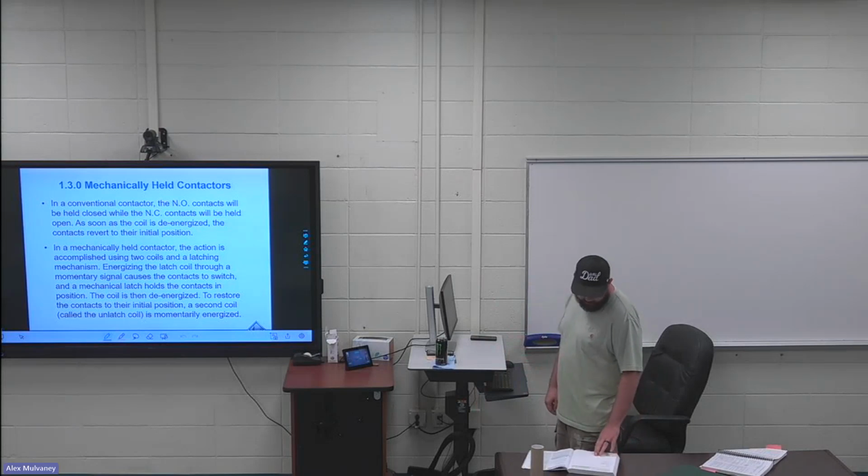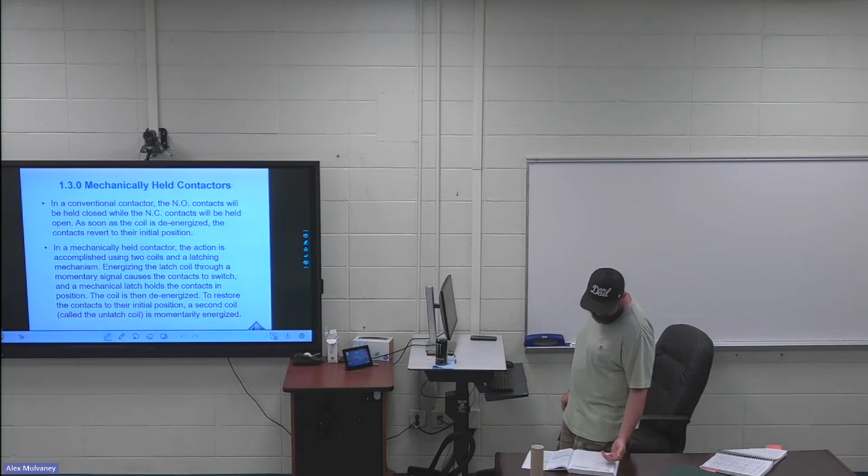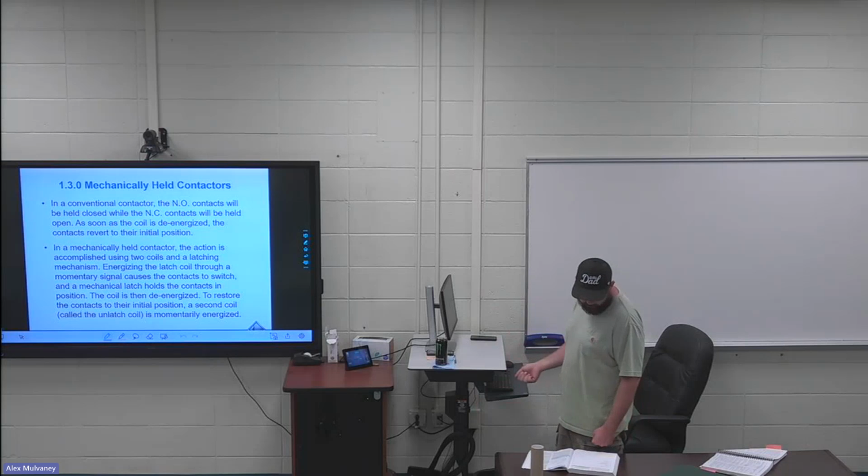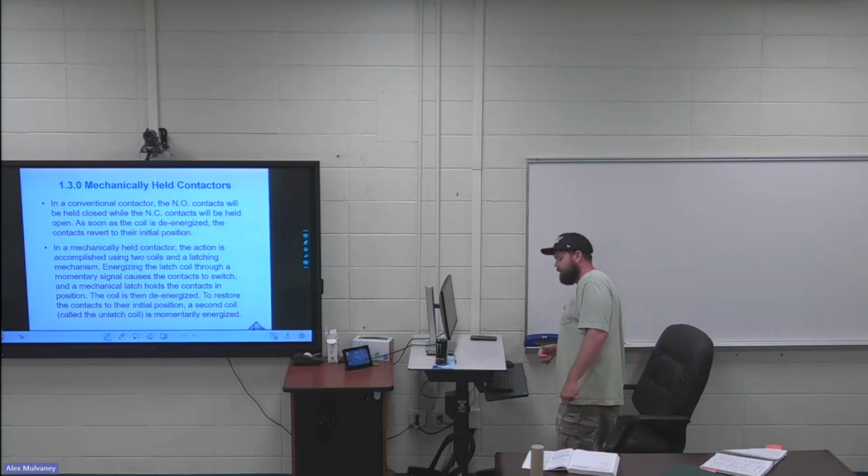Last paragraph on page 8 is important. I've got 2 highlights that come out of that one paragraph. Mechanically held relays and contactors are used when the hum of electrically held devices would be objectionable, such as in an auditorium, a hospital, a church, and so on. So places that are quiet need to have